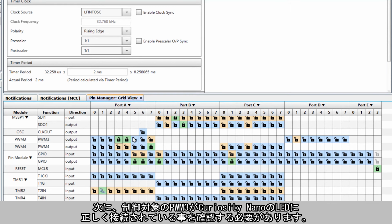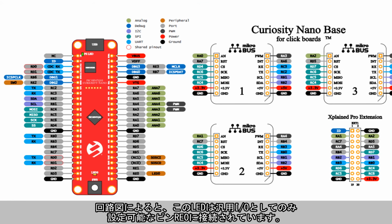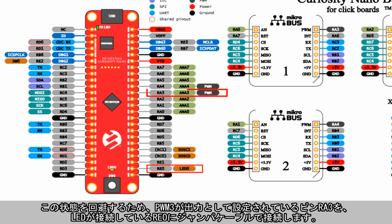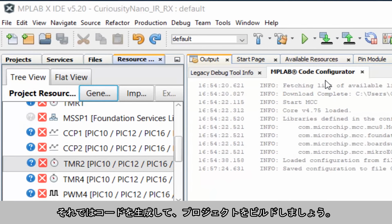Next, I need to make sure that the PWM3 module that we learned earlier is the one we are controlling is correctly routed to the LED on the Curiosity Nano. According to the schematic, the LED resides on pin RE0, which is only configurable as a general purpose I/O. To get around this, I'm just going to use a jumper cable to tie pin RA3, where my PWM3 module is set as an output, to RE0 where the LED resides. Once this is done, we can go ahead and hit generate code and then build the project.